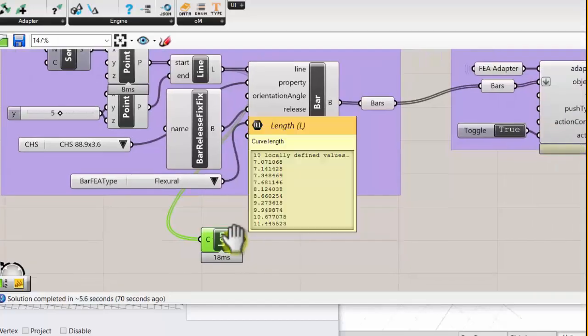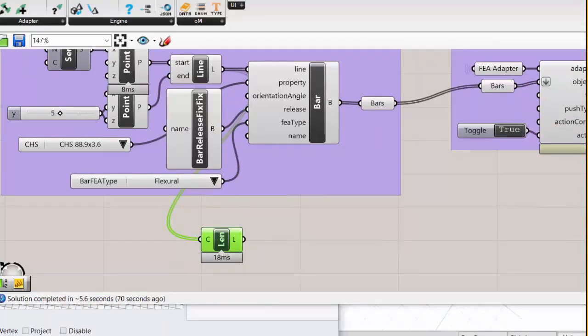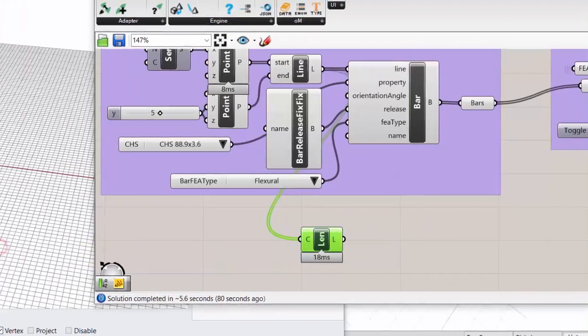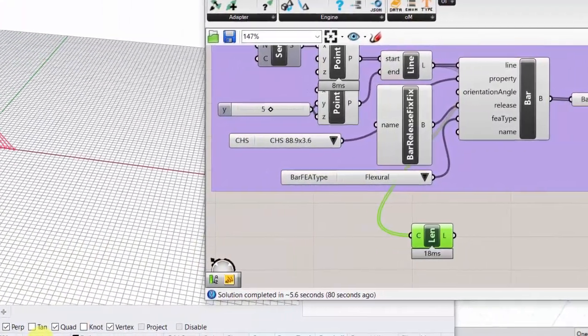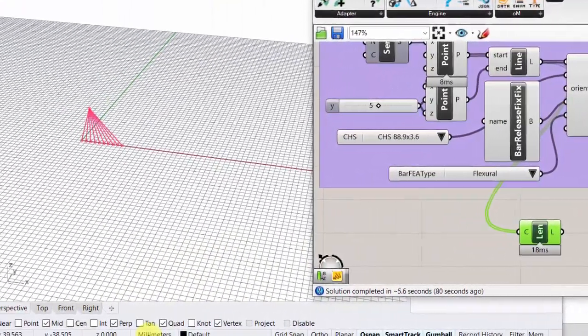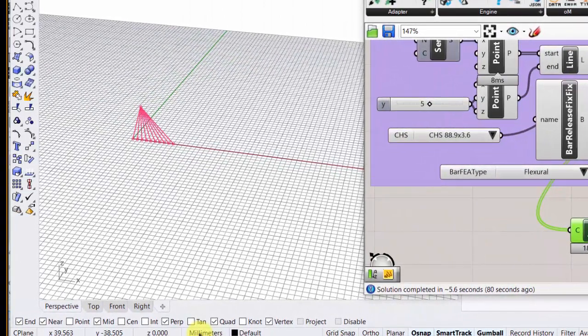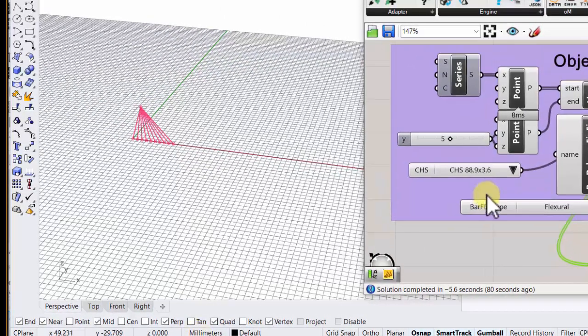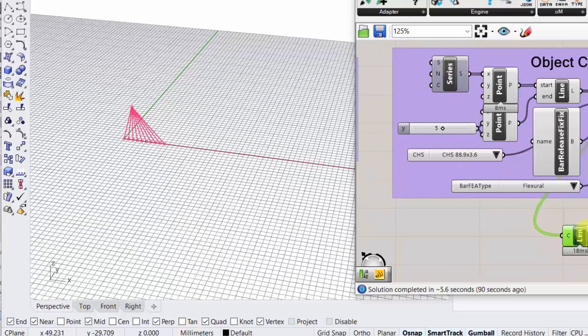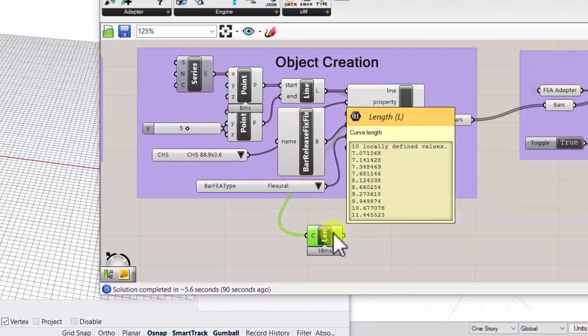The key is what you normally have to do first, no matter what: right now if you're looking in Grasshopper, my model's in millimeters, right? So that's going to be a problem. Now I happen to accidentally put in here numbers that when you interpret them, those numbers are 7, 8, 9, 10. So they could be on the orders of meters.